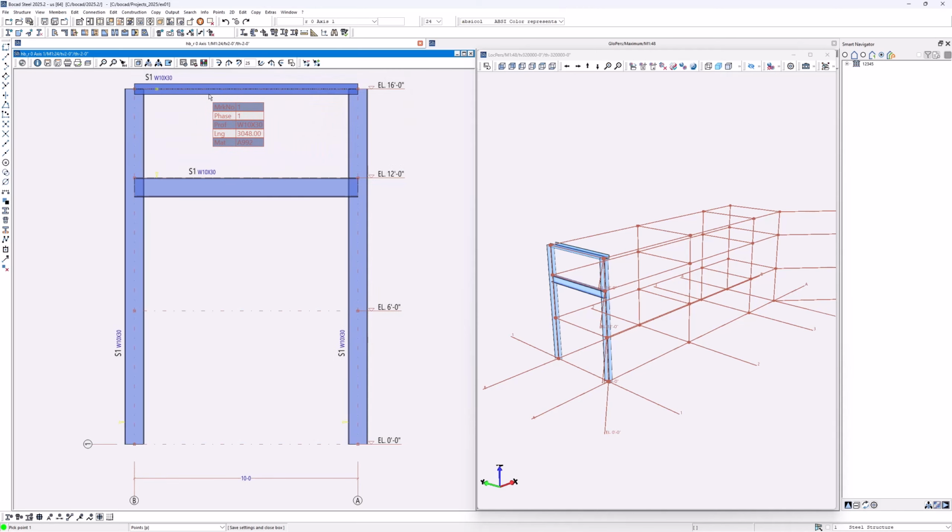I'm indeed seeing this in top view. If now I'm in a 3D environment, then it's a little bit different. My UCS is the 0 level, that flat horizontal level. So the UCS will be related to that view. That's the only little thing you really have to think of when modeling in a 3D environment as compared to a 2D environment.